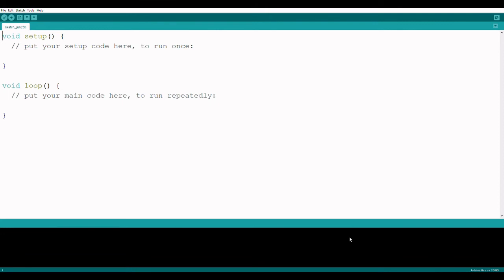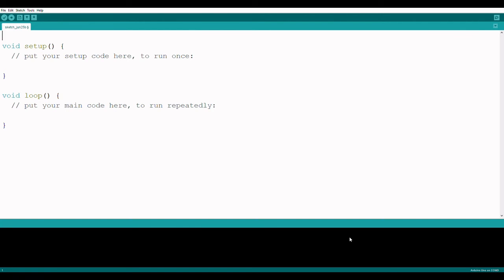So now we move on to programming. First, we have to declare our variables. These are going to store our data that we can reference throughout our code. Number 1, for example, the green variable represents the pin that the green LED is connected to. Now in our case, our green LED is connected to leg number 10. Our yellow one's at 11 and our red one is at 12. So you just have to set them up by keeping in mind which pins are which.